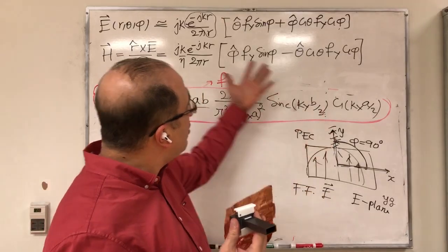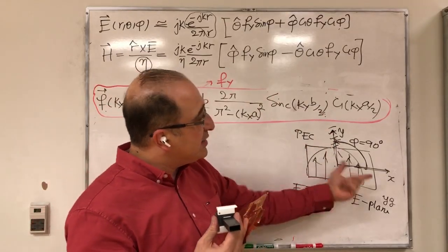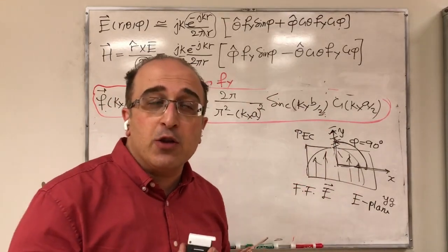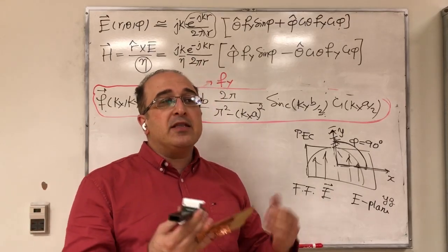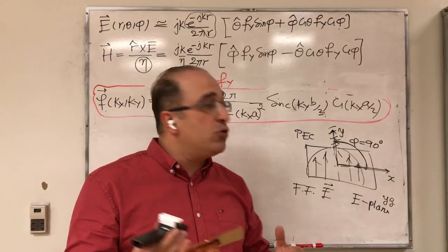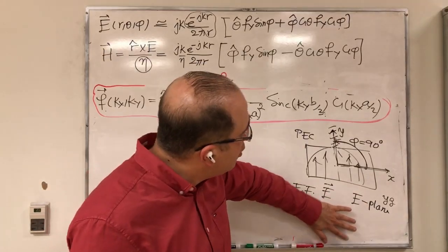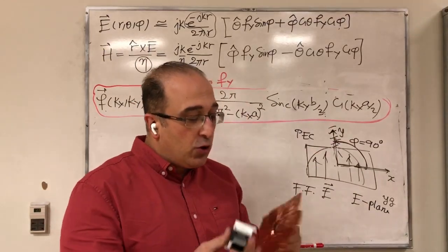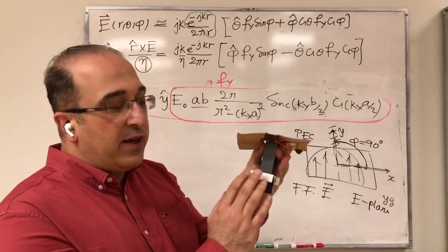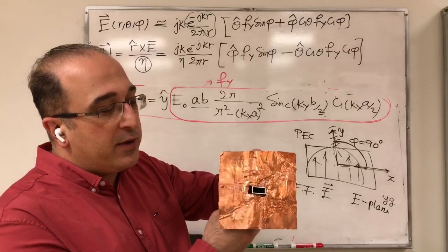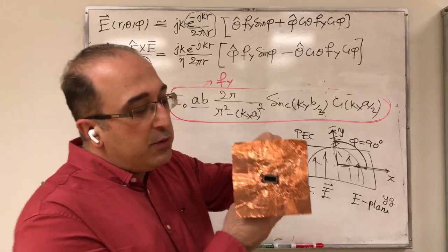In fact, this is from my previous lecture. It's a half cosine in the fundamental mode, which we explained. It is TE10. Then we said if we want to know the far field, we need to know the electric field over the whole XY plane. To handle that, let's assume this waveguide's aperture is mounted on a PEC plane.